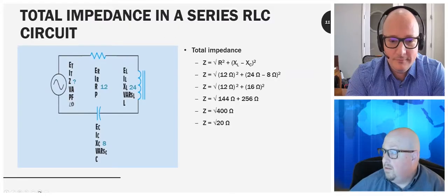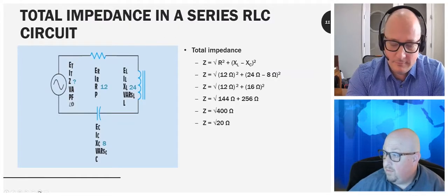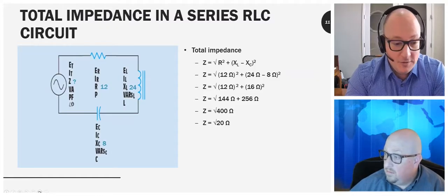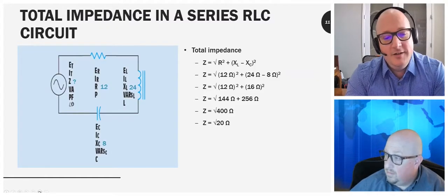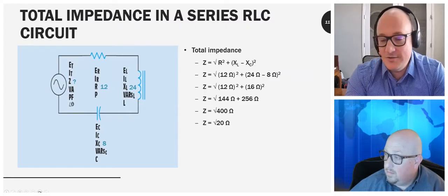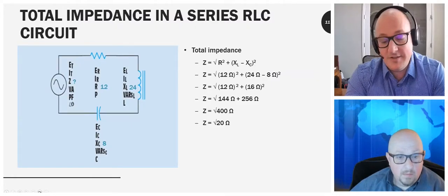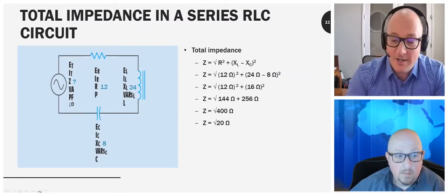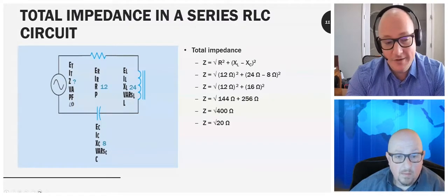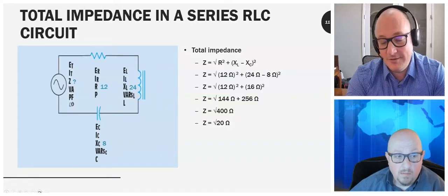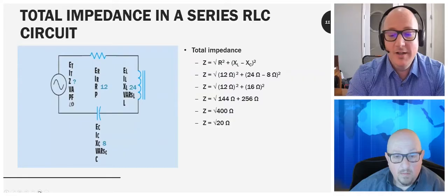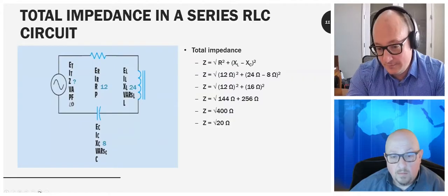Okay, so here we are. What do we have? And so for impedance, columns and rows, you'd have to just kind of, I know a lot of instructors also refer to this as like, let's table these values, let's put them in a spreadsheet. So I take all my E values, what's the applied or total voltage, what's the volt drops across the resistive component, the inductive component, the capacitive component, and that's how we form a row.